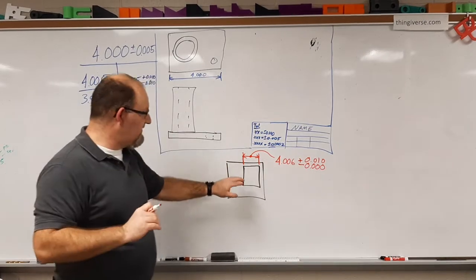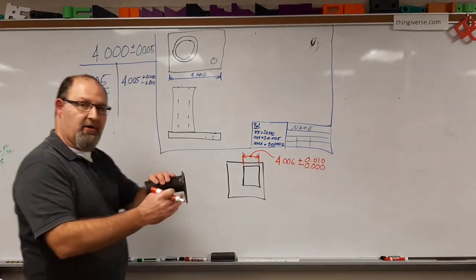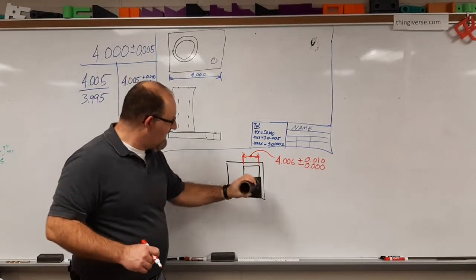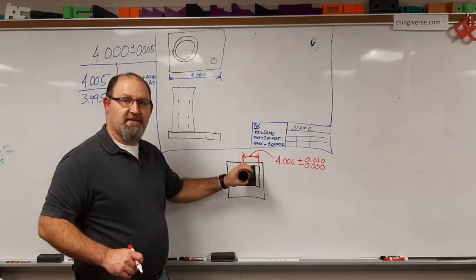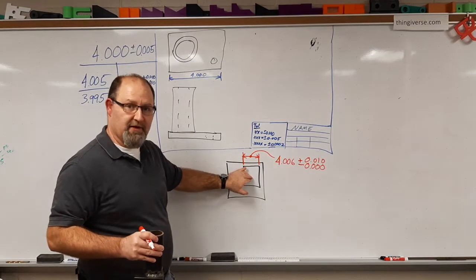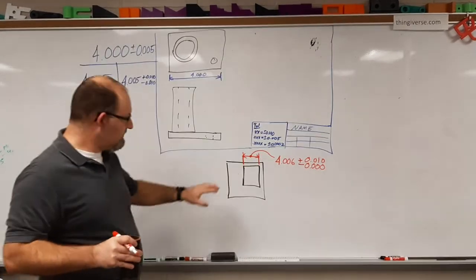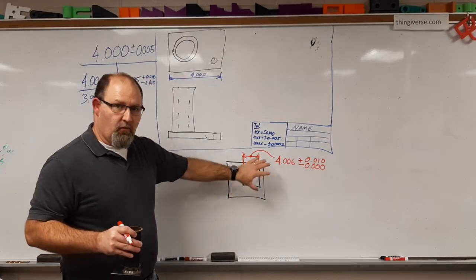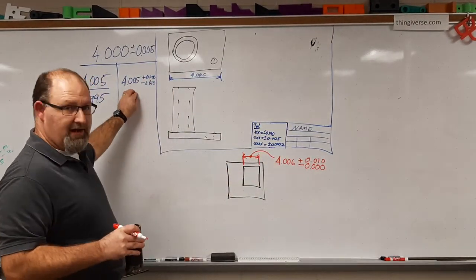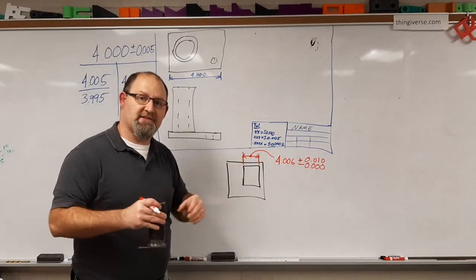This now ensures on the engineering blueprint that so long as that part is manufactured in the tolerance zone, this plate will always fit in there, regardless of who makes the plate with the hole, regardless of who makes the plate with the pipe. So we have now covered why you might set an upper or a lower limit, especially with regards to mating parts.